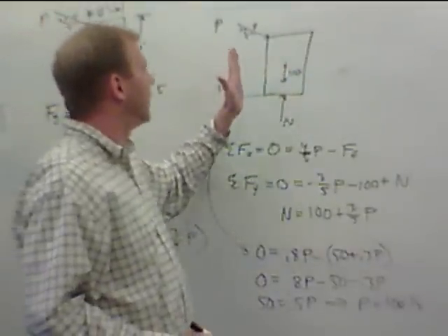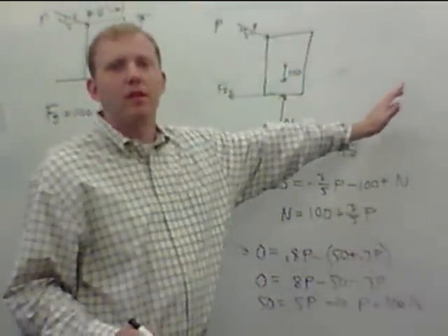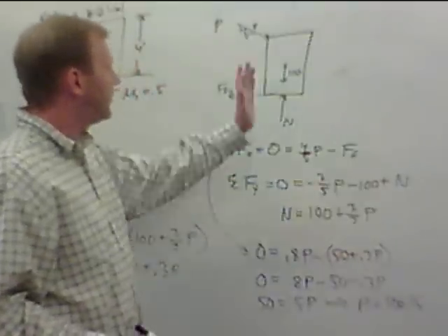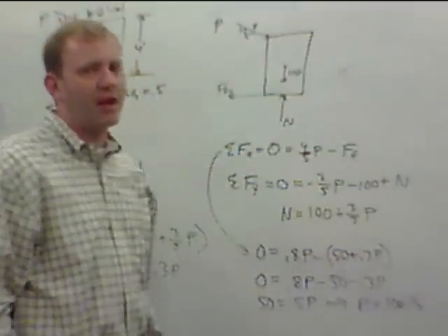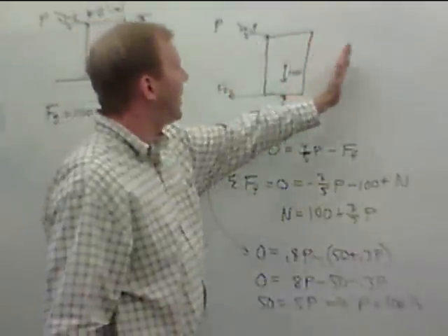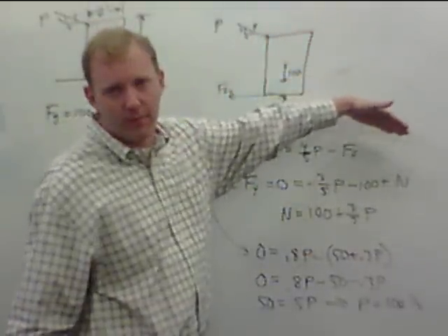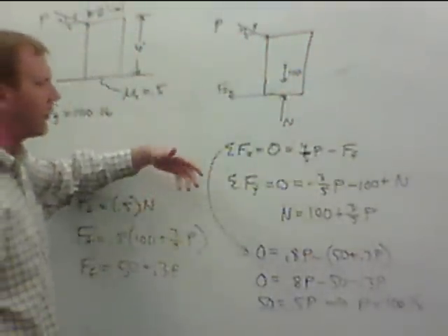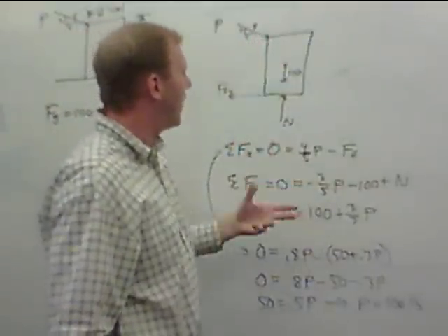Okay, this is 100% correct if the question is what amount of force would cause this block or crate or whatever I called it to start sliding. Okay, the reality though is this thing is not necessarily going to slide. It has another mode in which it could move. This thing could either slide or it can tip over. Okay, you can tip things over, obviously. In this case, we have to check for that.